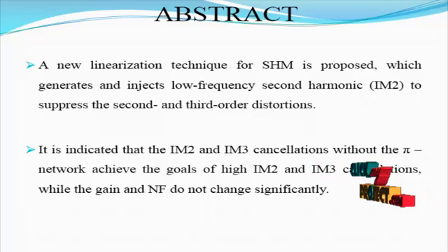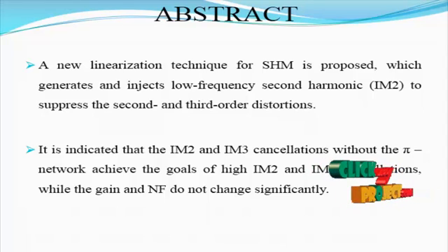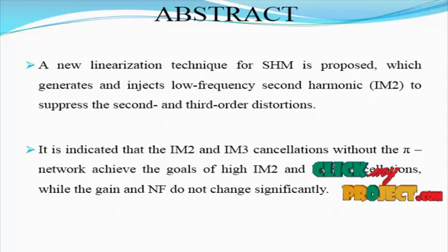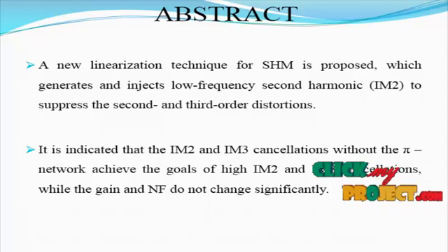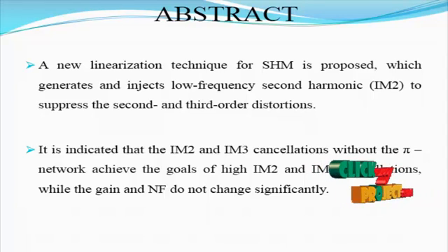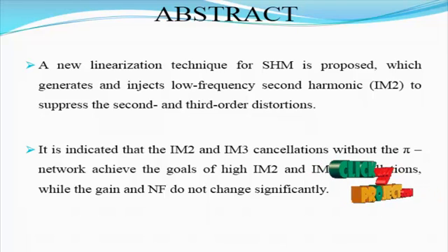One of the most challenging problems is the DC offset. A consequence of self-mixing is the leakage of the signal from the local oscillator to the mixer input. The LO signal is usually strong and leaks through the parasitic capacitances. The DC offset may cause adverse effects such as saturation of the next stages, noise, performance degradation, and nonlinear distortion.